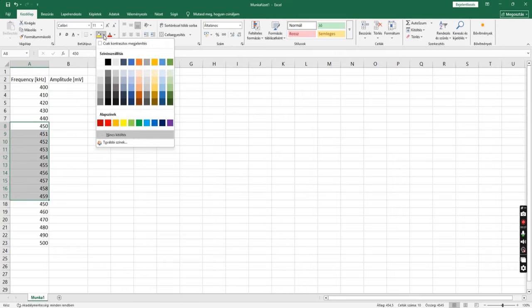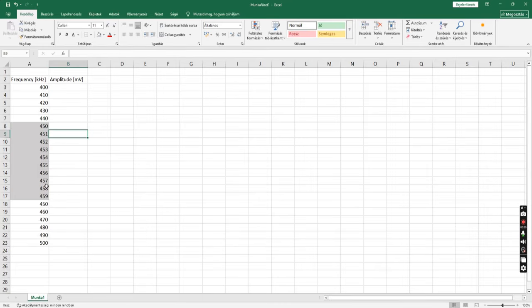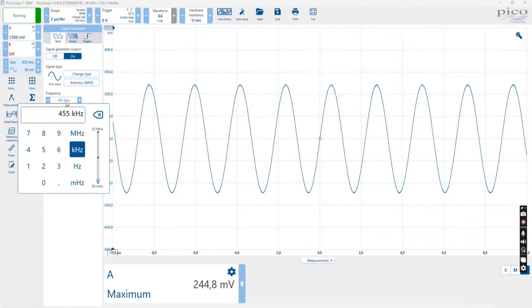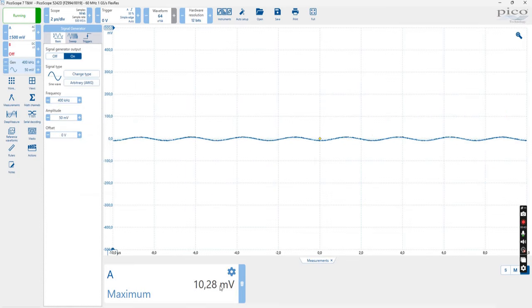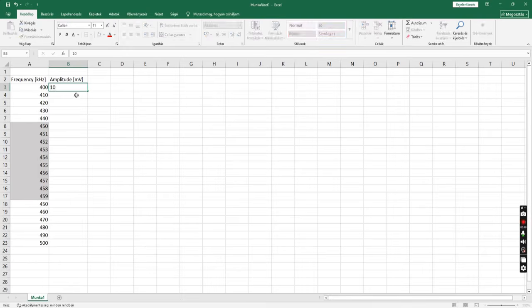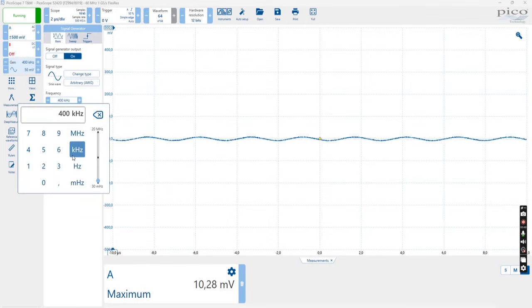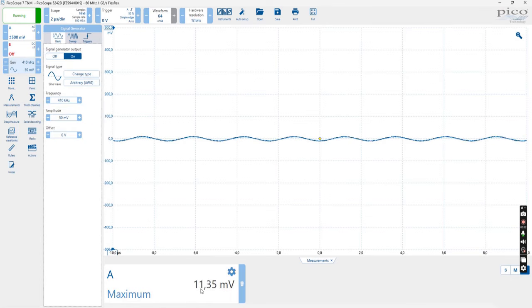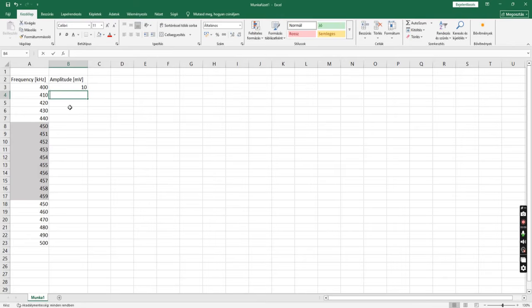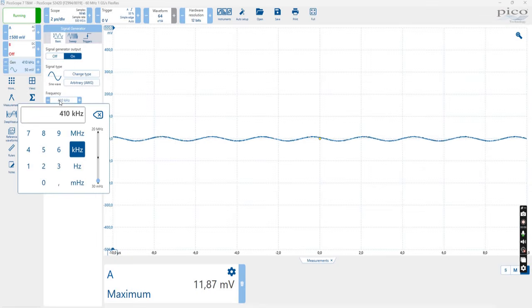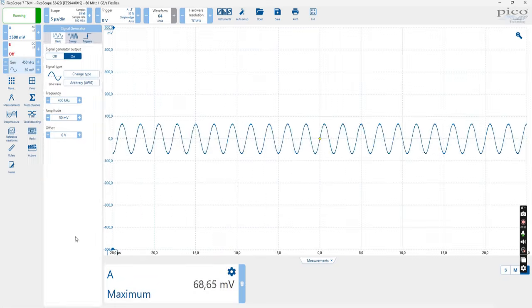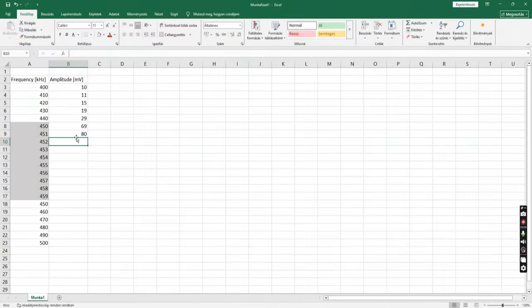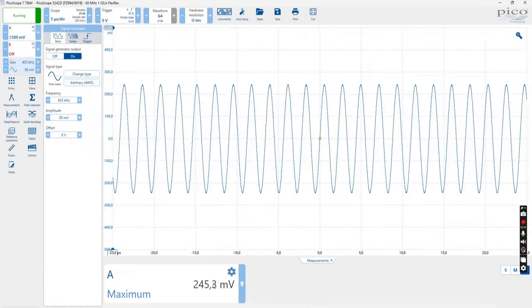Here's a tip: the closer you get to the expected peak frequency, the smaller the frequency step should be. We will check the first two measurement steps, and after that I speed up the video so the final result appears quickly. With a basic oscilloscope, you can do this using the scale divisions, while in my case the scope directly displays the amplitude.